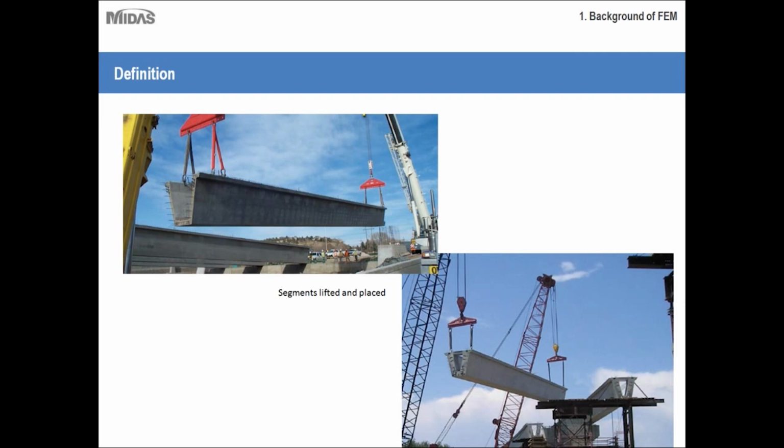cranes have failed to lift a section because they were not properly supported at correct intervals. So you have to be a little more accurate, a little more cautious when you are dealing with these types of bridges and you are lifting them. There are different types of sections. This is the conventional segment, and this is one with the diaphragm. So they are applied at different locations.